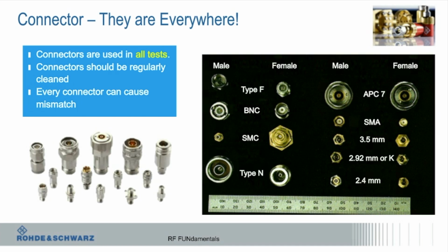If you only want to go up to 26.5 gig and your thing is 2.92, it's fine. Bolt them together, but just don't expect it to work automatically up to 40 gig. SMA will technically mate with these two, but you've got to be really careful because you can really damage those. N-type, that's the big one, usually up to 18 gig. Higher power is primarily why people use that, although it's much more rugged. It's the most rugged of these.